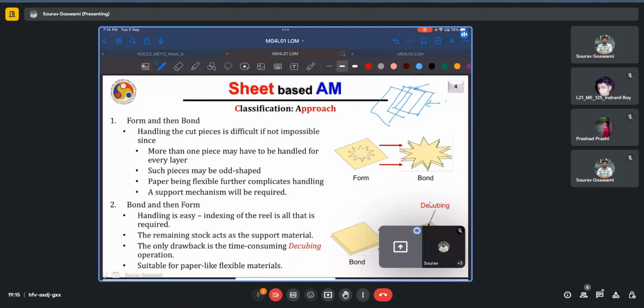So I know what I need for layer 1, layer 2, and layer 3. I can either previously cut out that shape, such as in this case, the star is cut out from this sheet. I can form these individual contours from each of the slices and then finally bond them together using any suitable means, such as thermally activated glue, some ultrasonic-based processes, or even plain adhesives.